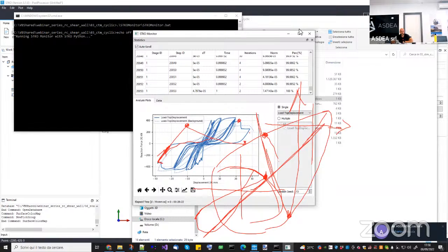Actually, in the concrete model we have the viscosity, so you can play a little bit with rate dependency, but with the simple Perzyna model. So I don't know if you had something better in mind for steel, but yeah, that would be nice also.